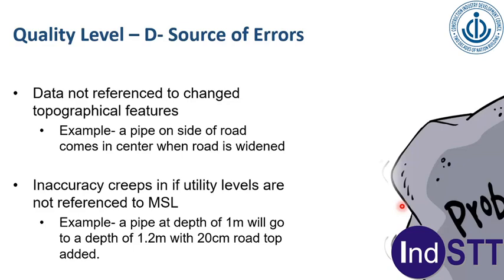Now, there are the most commonly used tools. As I said, if you really go to the list, there are more than 17 to 19 different methods listed. But the fact is that in an urban environment, the most commonly used tool is GPR, ground penetrating radar. This can detect both metallic and non-metallic utilities. It of course has capabilities and limitations. This session is too short to go into detail. The idea is just to give you an overview of SUE. There are a few videos referred to here. You are more than welcome to watch these videos.